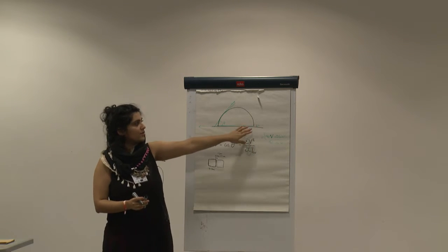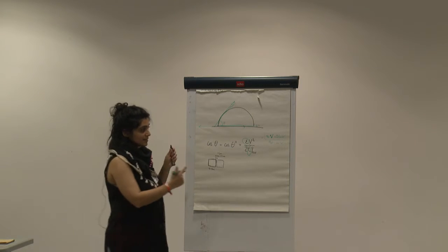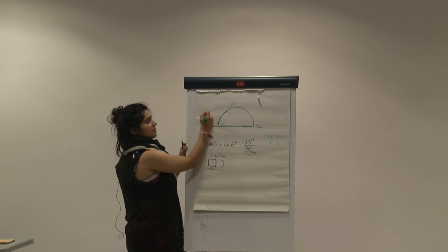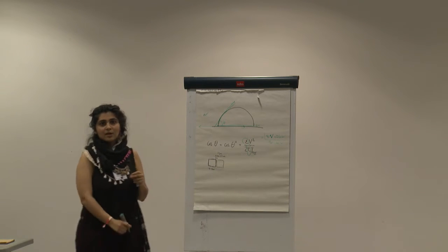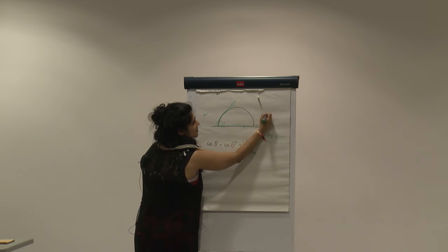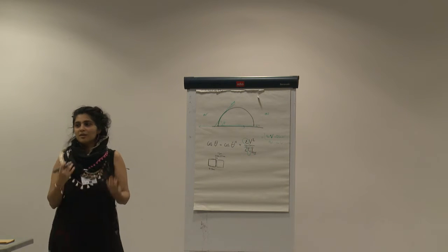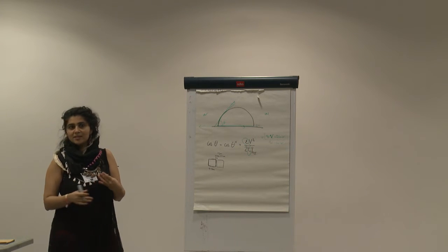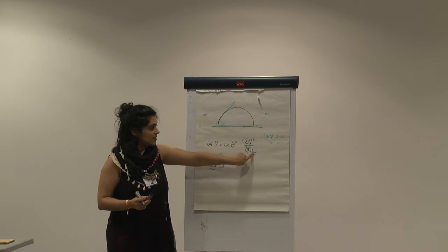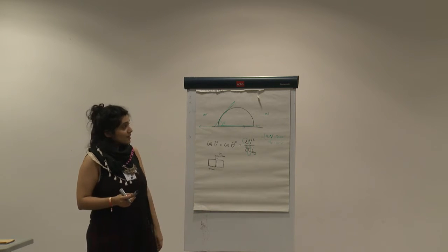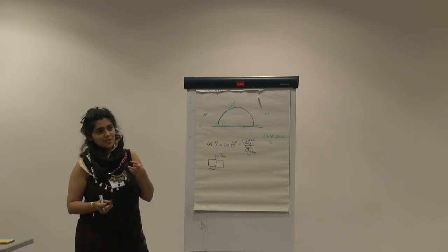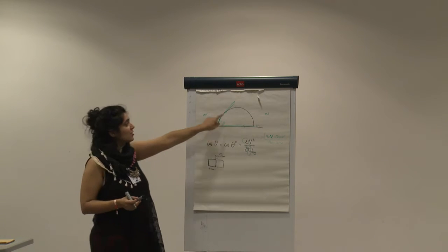They depend on the layer in between and the liquid-vapor interface. So we usually want to move them in air. Well, let's put it like this: it works better if we move in oil, since we are targeting aqueous droplets, DNA that dissolves in water and stuff like that. Then it's better to move in oil, because this value is much better. However, if we have cells inside, they have oily membranes and they dissolve in oil, so then we want to move them in air.